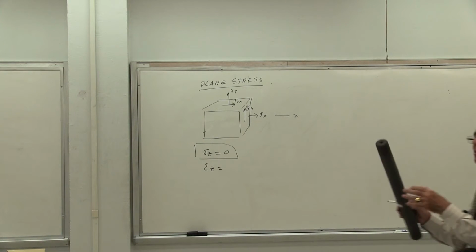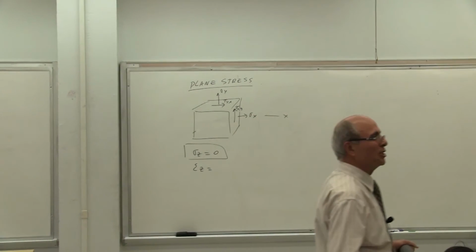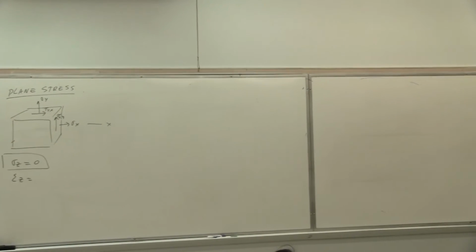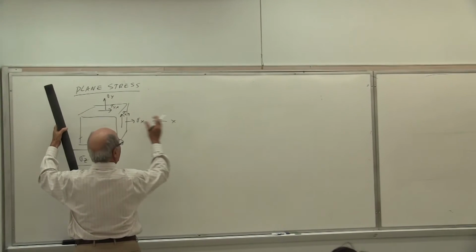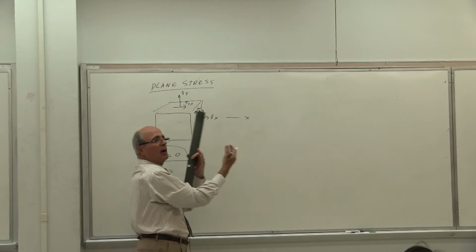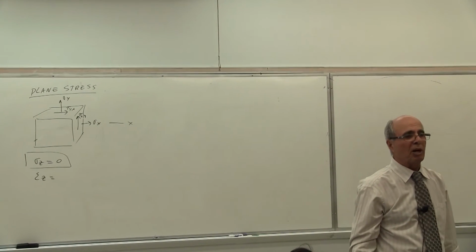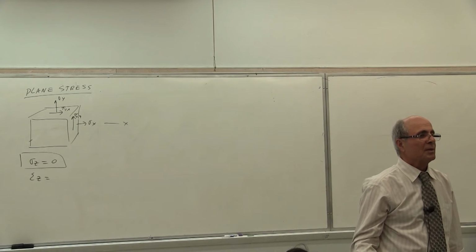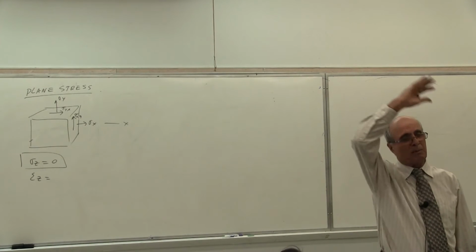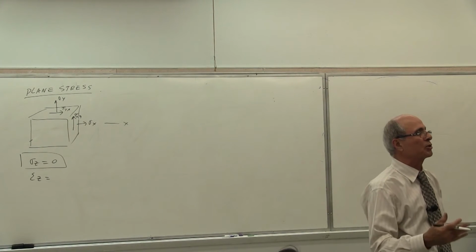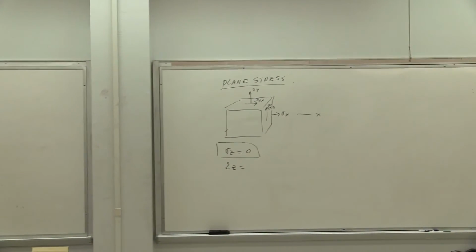Now let's assume that you have put some gauges on, as part of the machine that you are designing, and you come up with this epsilon x. I don't think this is the solution in your handout, but the problem might be there, or might not. Nevertheless, write it down. Let's say that we measure epsilon x equal to 340 micro. Remember that we are expressing that in micro because we don't want too many zeros there. Is that correct? Micro is 10 to the power of minus 6. Let's say that we measure epsilon y, which is given to you as 110 micro.